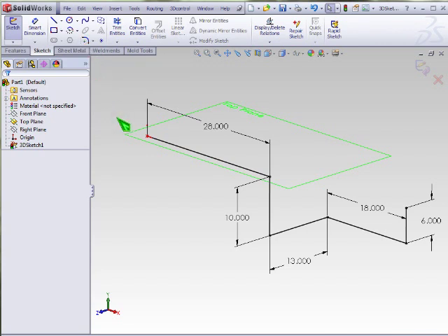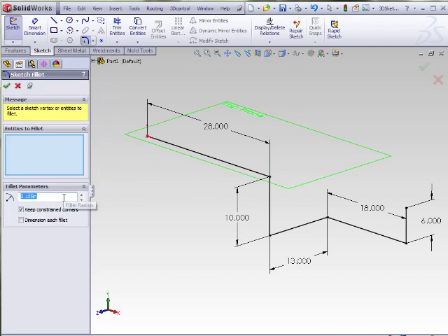You can use a number of your various sketch tools, such as creating sketch fillets in a 3D sketch. That's what we'll do here. The technique is really no different than if you're working in 2D. You can pick the points, pop those fillets in. Of course, in 2011 we get a preview, which is nice. Alright, so there's our sketch fillets.